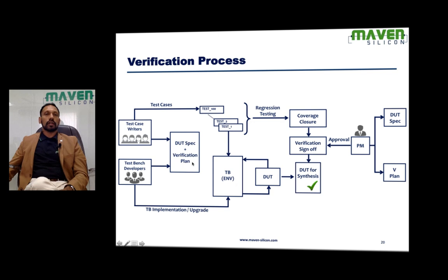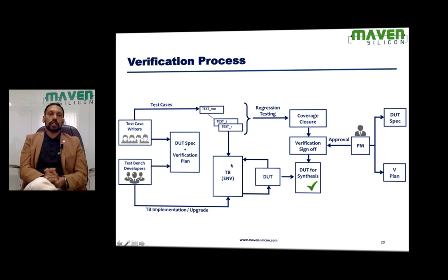In this case, they are going to look at the Testbench architecture, and based on the architecture, they are going to write the Testbench program. Also, they will instantiate the DUT as part of the Testbench, and then they try to verify whether the Testbench works properly. So they are responsible for finding all kinds of bugs in the Testbench or verification environment.